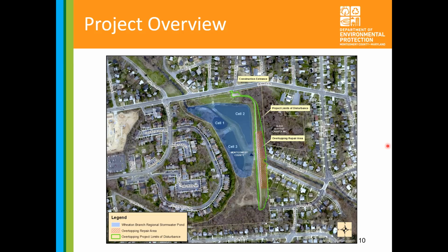You can't put any kind of woody vegetation, and that's for obvious reasons, because their root systems extend into the dam and can actually be a point of compromise, if water finds its way along the roots. And no, I get it. I'm not asking for the woody stuff. I'm asking that whatever vegetation is taken out of there gets put back in with something that goes with the habitat. If we're going to use a different mix from somewhere else, we should be trying to replace things in this area with native plants.